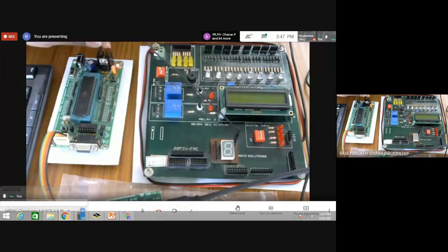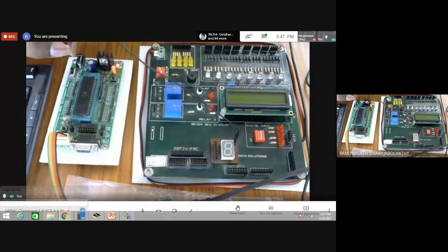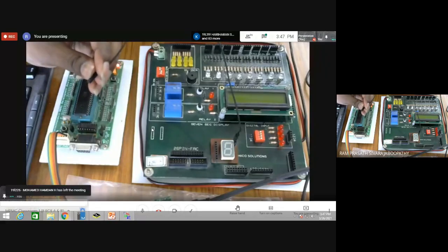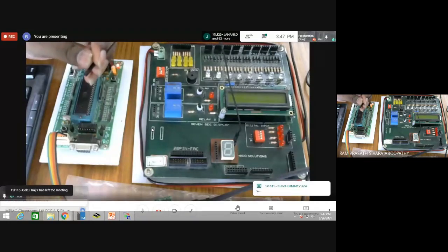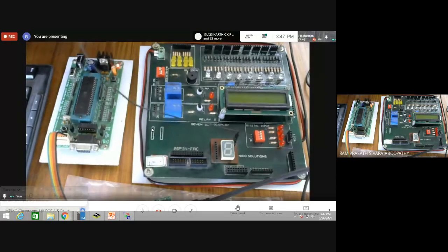Kindly type it in the chat. On the right hand side of the 7 segment LED, what did we say the connector is? Common anode pin. Both are common anode pins, there are two holes, both are common anode. Where do we have to connect the other end? We studied where the anode pin gets connected. Kindly type it in the chat so that I can know. Otherwise unmute and tell. Yes, VCC. On the microcontroller board, we see where the 5 volt is. Yes, so it is here.